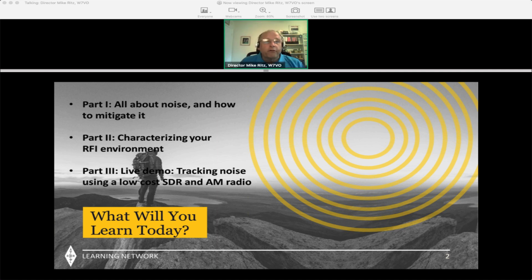So we're going to do this in 3 parts. Part 1 is all about noise and how to mitigate it. Then we're going to look a little bit at how to characterize your own RFI environment, and follow that with a live demonstration. We're actually going to track noise and look at some things that are noisy and things that aren't noisy using a low-cost SDR, software-defined radio, and also just a cheap AM radio that I picked up at the Goodwill store.